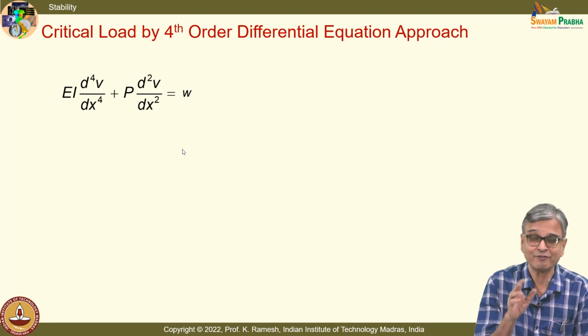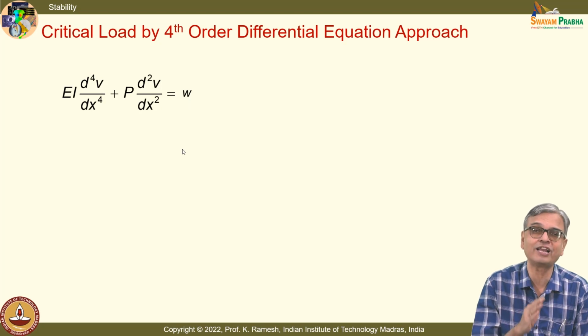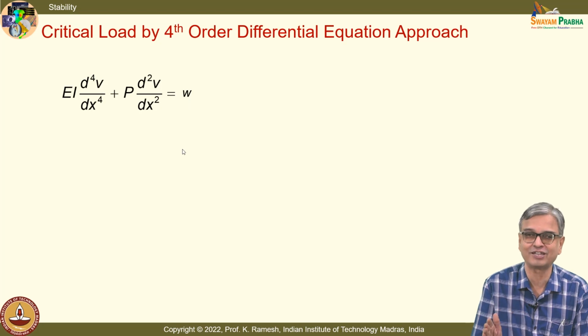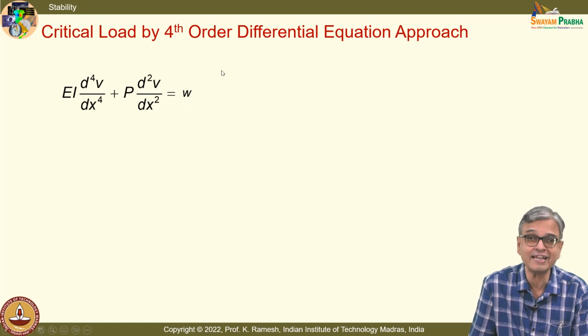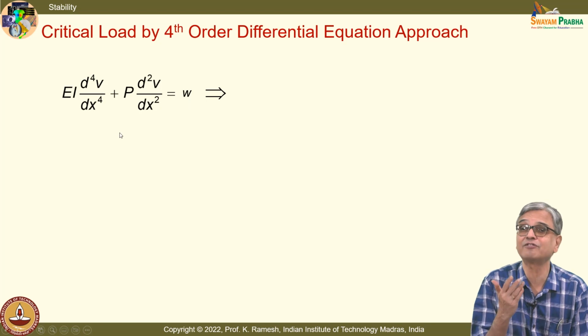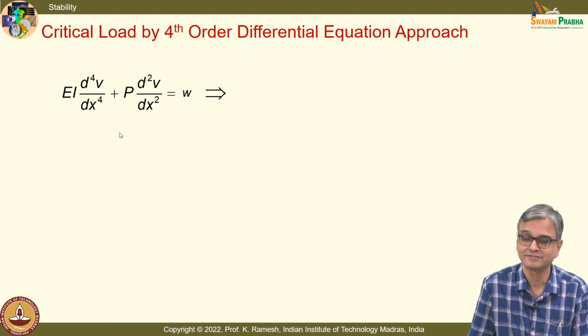Fine. We have not taken that as non-linear. In fact, it is very surprising that when Lagrange and Euler analyzed, they had taken the non-linear expression and then did all the derivation. Fine. They have also indicated that. But here we have used only a linearized moment curvature relation. So, in that sense, it is an approximate expression. Where does this hit in our solution? That also we will see.